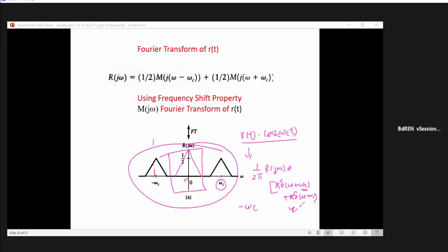So what happened then? With this multiplication with the carrier, you are bringing back the spectrum of your message signal to the original location, but an amplitude factor will be there. Then you can tune the gain of your low pass filter to compensate for this amplitude. You just apply this after receiving your modulated signal: again you multiply it with your carrier generated at the receiver, the local carrier, by using a local oscillator.